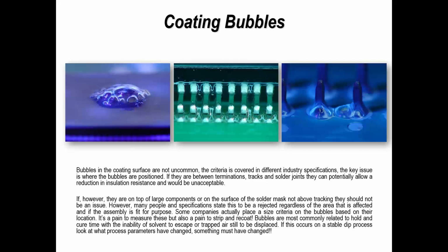Now, I want to be realistic and sensible here that when lead-free was first introduced and tin became the dominant surface on every type of component that we soldered, there were quite a few cases of tin whiskers. I certainly haven't examined, for quite a few years now, probably about 5-6 years, any examples of tin whisker failure.